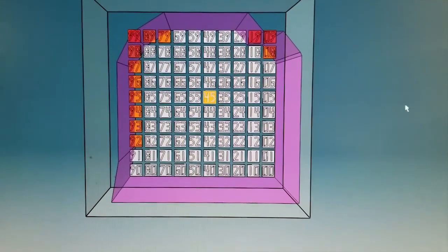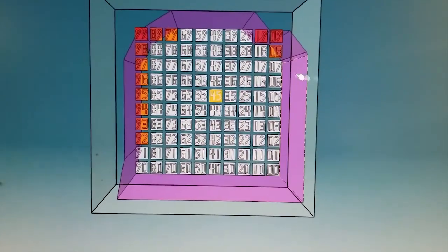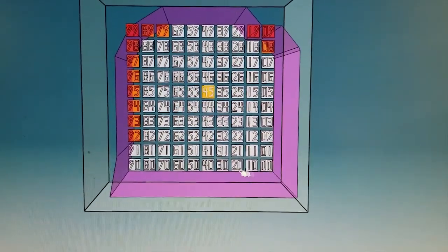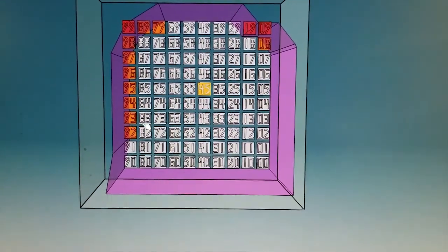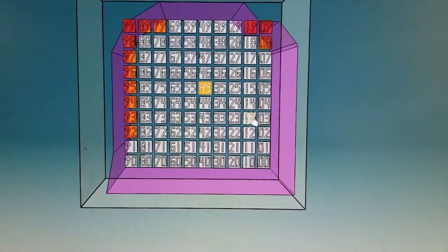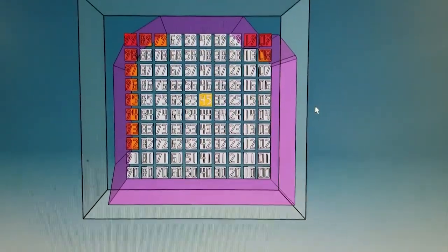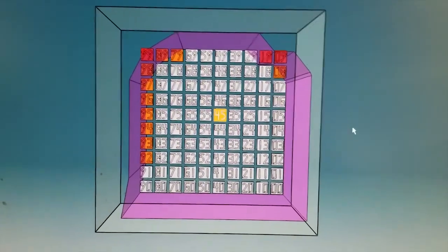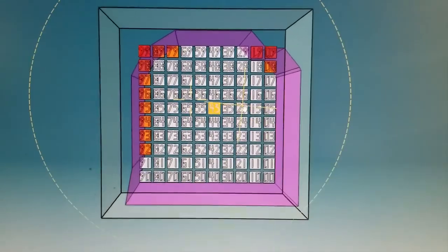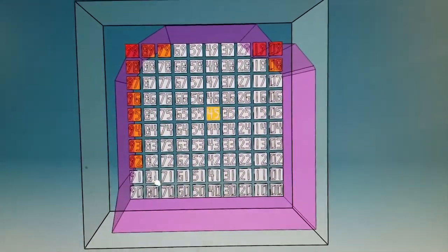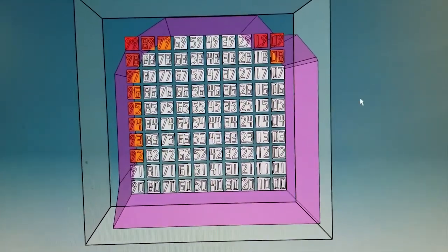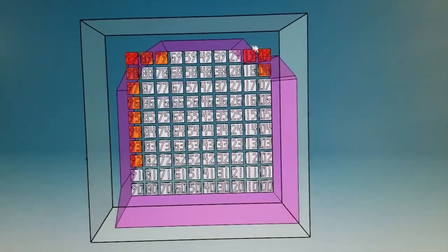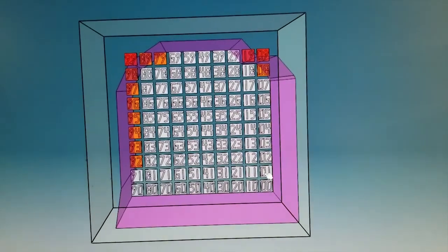I might do a couple more tests at slightly cooler temperature and see which of these squares become red and which become orange, and then I'll have to make sure I work inside that smaller volume. I know that Sintratec recommends that you stay within an 11 centimeter square, and by using this grid you can identify exactly where you can push the limit. This doesn't look like a square. In fact, this corner here is kind of useless and that corner is useless, but surprisingly